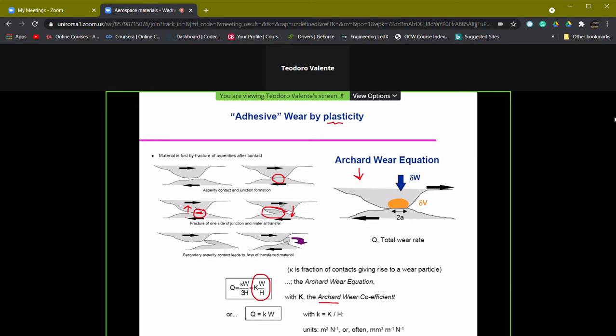And so if we need to break the welding in order to allow the movement to still exist, the fracture will be developed on the weaker materials, but under the surface of the materials itself, where work hardening has not been experienced because we have not, to a certain depth, overcome the yielding strength of the materials. That is, the fracture will be present in the area in which the materials has not been reinforced in terms of resistance by work hardening.